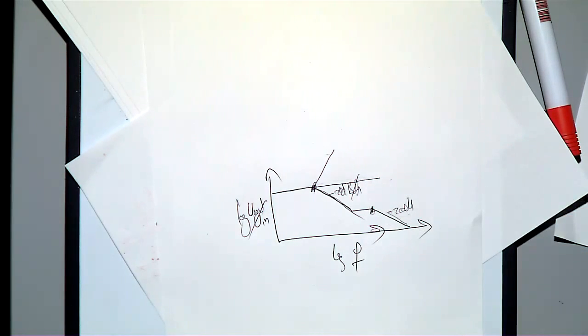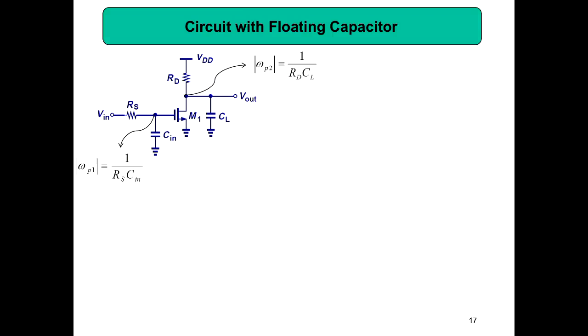And then here also, if you introduce a 0, you can make this straight again. You know what I mean? So poles and zeros can be cancelled, which we will not be studying here. That is another big topic in frequency response, cancellation of poles and zeros. Now we are identifying poles because that is important for amplifier design, because we don't want the gain suddenly dropping. We want to find out where and how it is dropping.